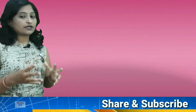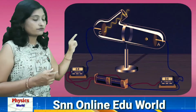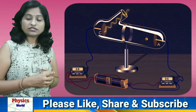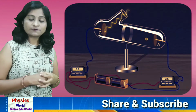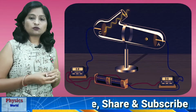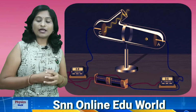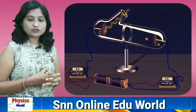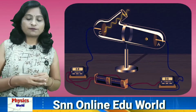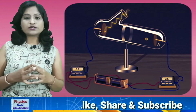Now in the working process, whenever light of suitable frequency enters through that window, it falls on the cathode. The cathode is photosensitive material, so it absorbs the photon energy and immediately electrons are emitted. These electrons must travel towards the anode, the collector, so the polarity of the anode must be positive.